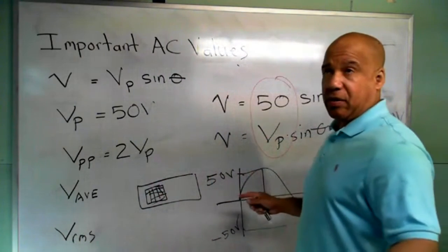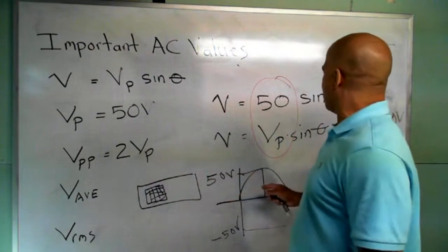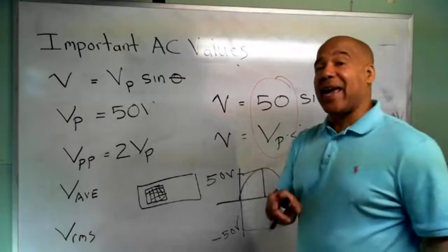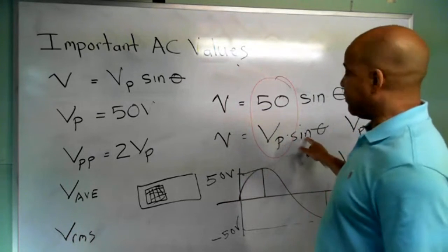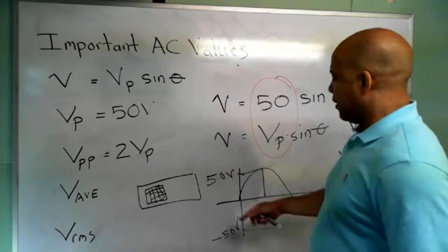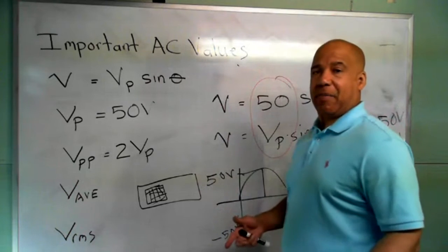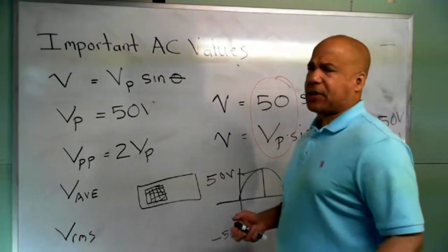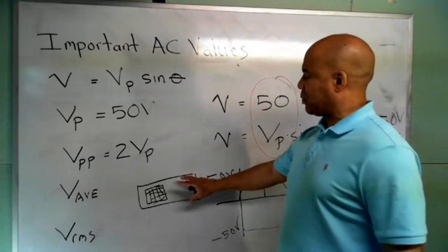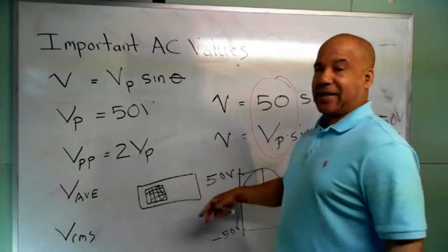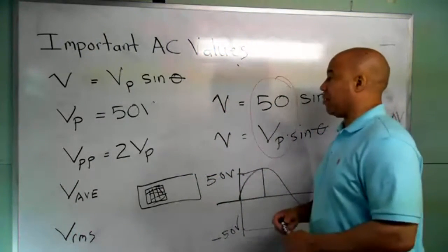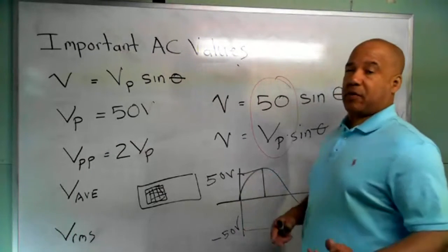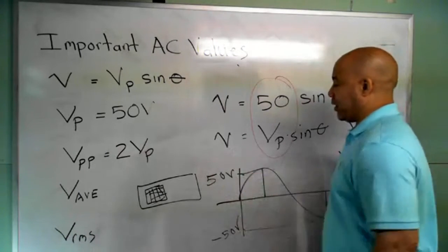But I think you guys are probably still doing your DC stuff. When you get to AC, you'll actually do this. You'll see the waveform. You can't measure frequency directly. Multisim may tell you, but in the actual lab, if you had the analog oscilloscope, you would measure the period, and then you would use that formula I gave you earlier to convert the period to the frequency. So you'll see this when you get to this in lab.